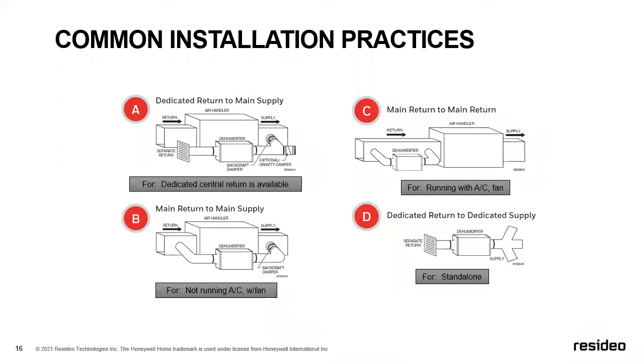First question for you in the training today would be, tell me how you have it ducted. If they said to you, I have it ducted supply, I'm discharging into the supply, maybe I'm pulling from the return, or have it dedicated. Your question there would be, well, are we running the dehumidifier when we're running the HVAC equipment?